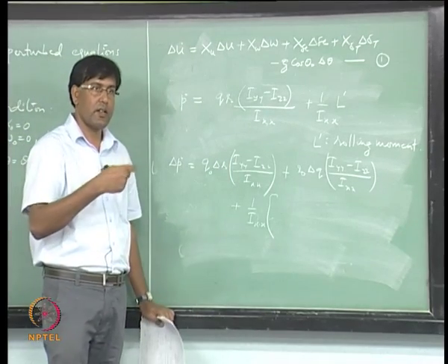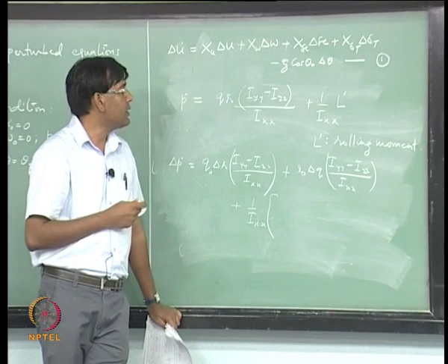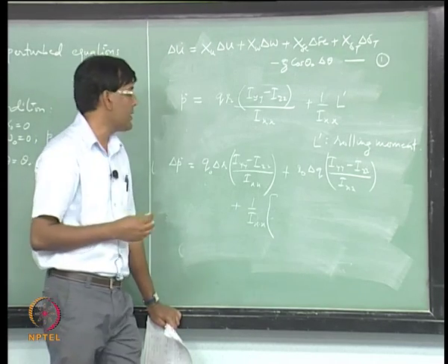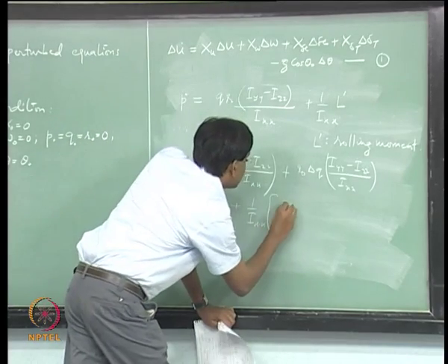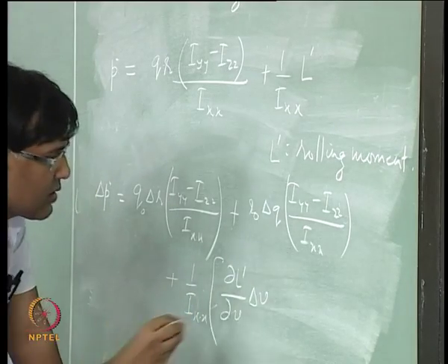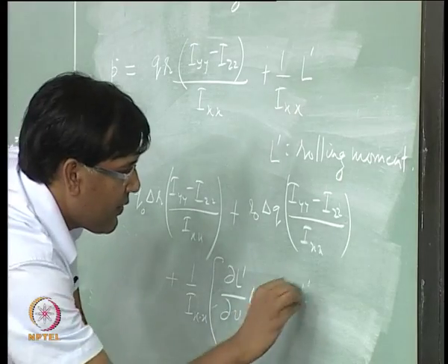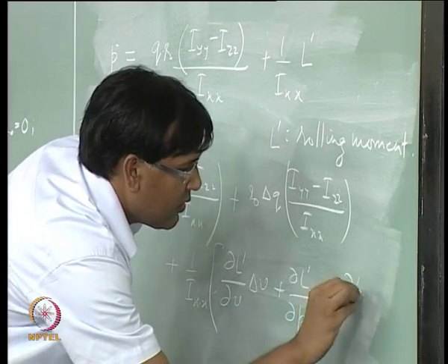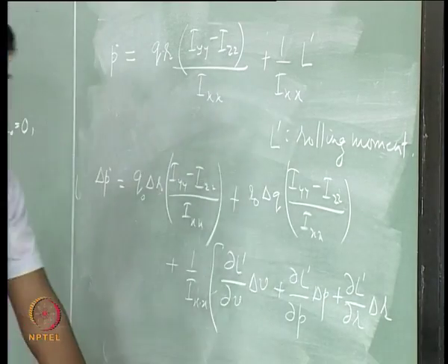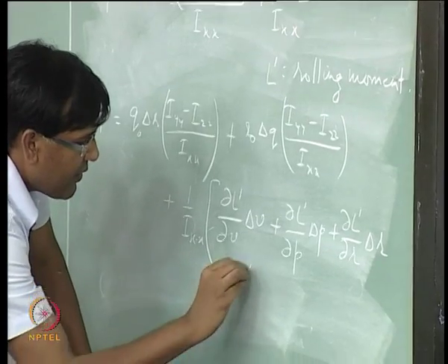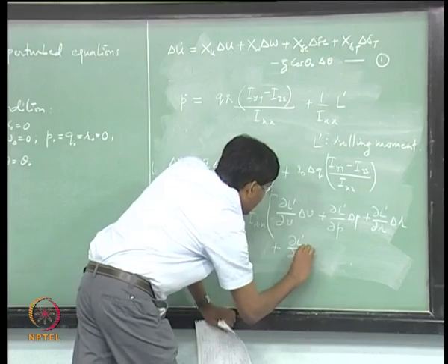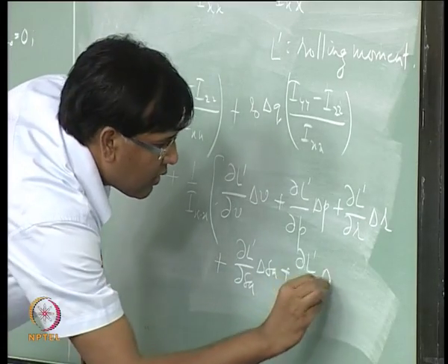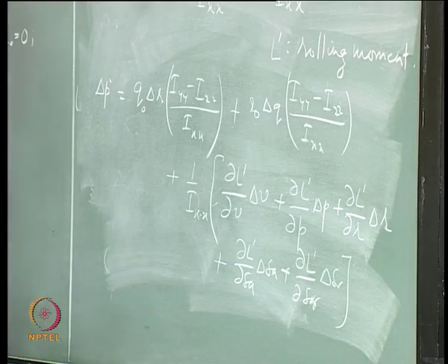It is going to be a function of the side velocity, or side slip angle, roll rate, yaw rate, aileron deflection, rudder deflection. So this can be expanded now.